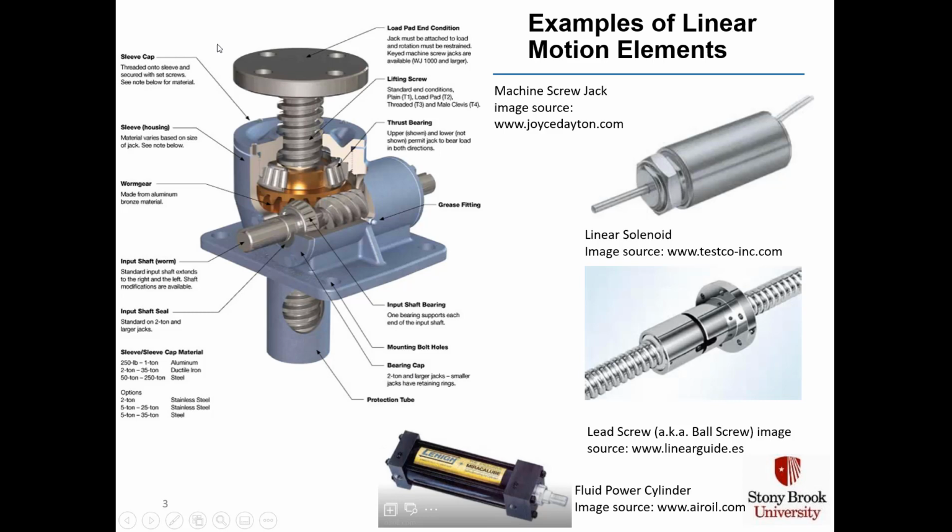This mechanism up top here is the most complex. It is a power screw. You have a motor that rotates the worm. The worm in turn rotates the worm gear. As the worm gear rotates, this thread goes through the nut and this thread moves up and down. On top you have the load pad, and that's where you would put a very heavy item to lift up and down.